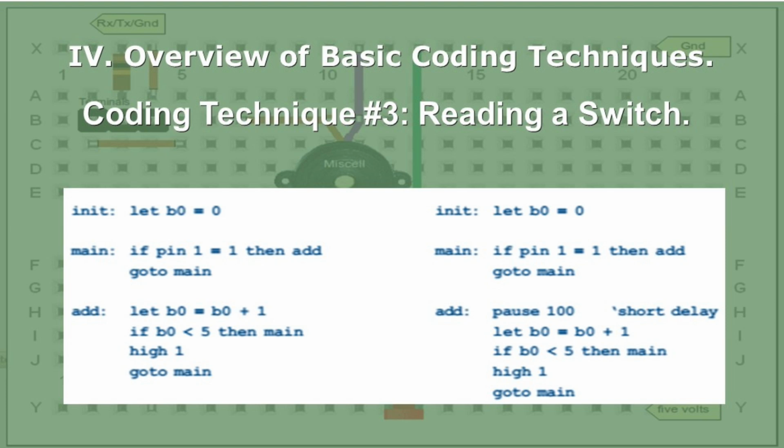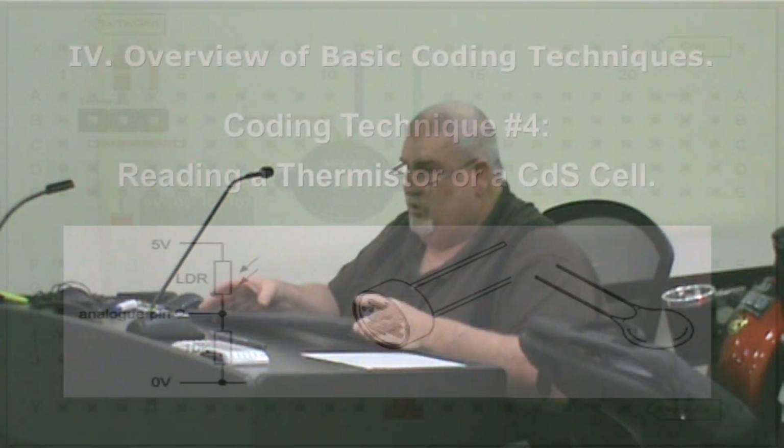And there's the code right there that has the delay in it. The code on the left is without debouncing, the code on the right is with debouncing. Notice they dropped in a 100 millisecond delay on that command before it began to read that port. So if the switch is down for 100, it counts it. If it's less than 100, it doesn't count all those bounces. And that's a great way to do the signal debounce, using a delay.